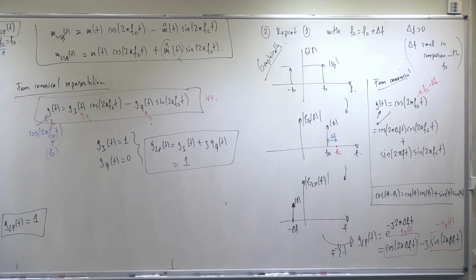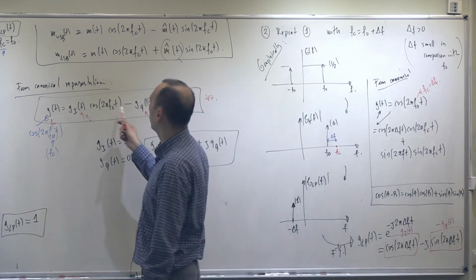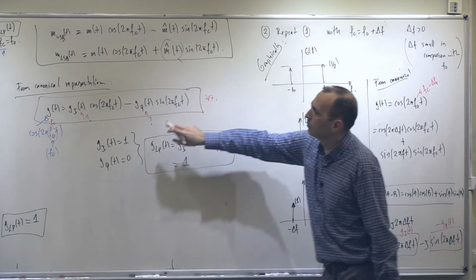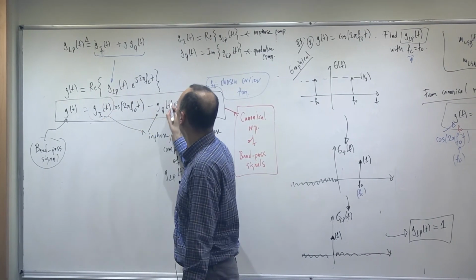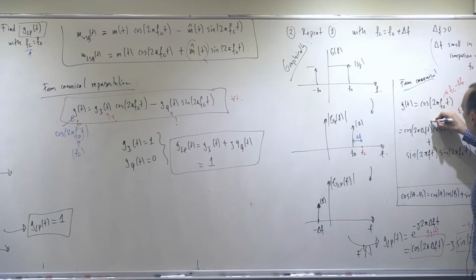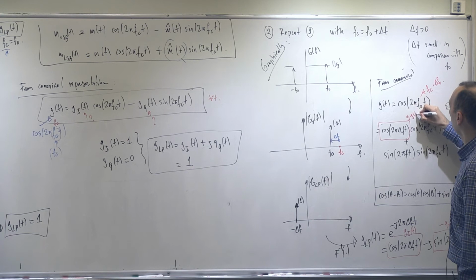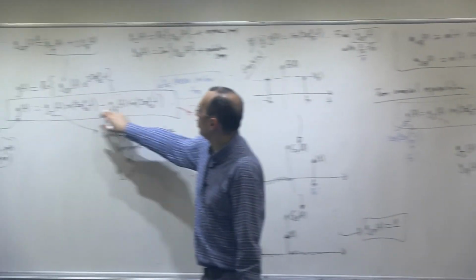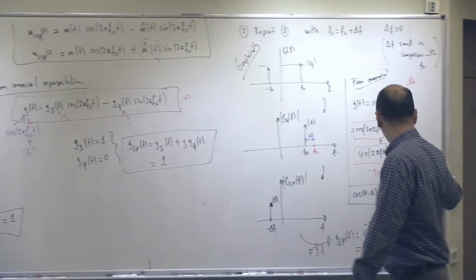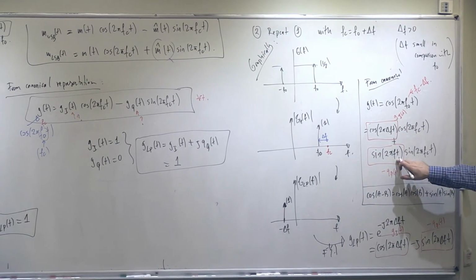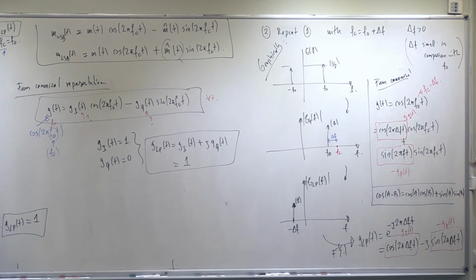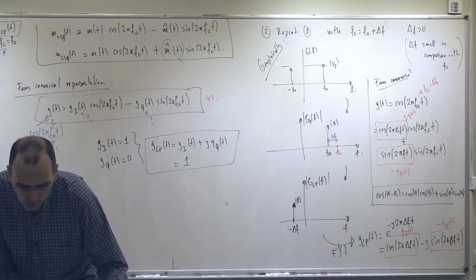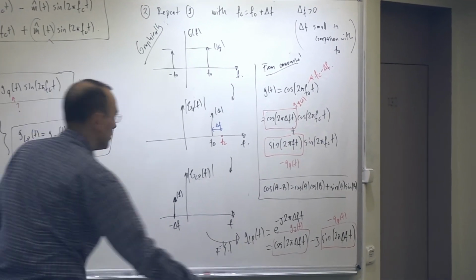That is it. So then, if g of t is like that, how about if I compare this g of t with this canonical representation? How can I find gi and gq? This is supposed to be gi of t, and this is supposed to be minus gq of t, because minus gq of t is the factor of sine. Very nice, I'm very happy. Minus gq of t is indeed sine, and this is equal to this. Again, it matches. Good news. So right now we have seen how to calculate this low pass equivalent. Now one more thing, and we will be covering today's topics.